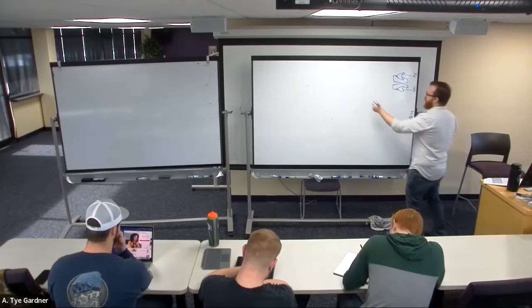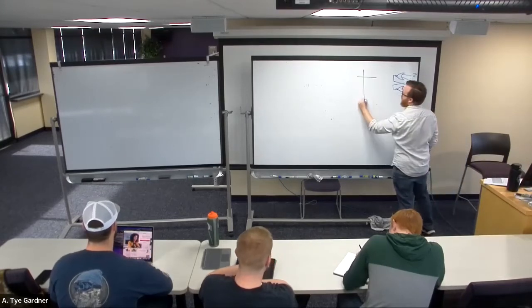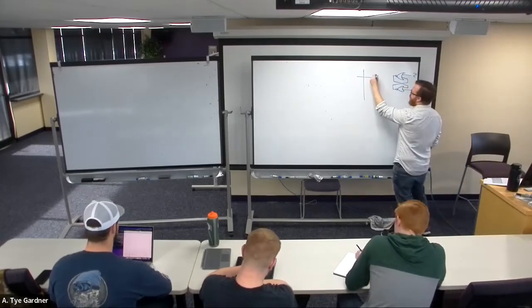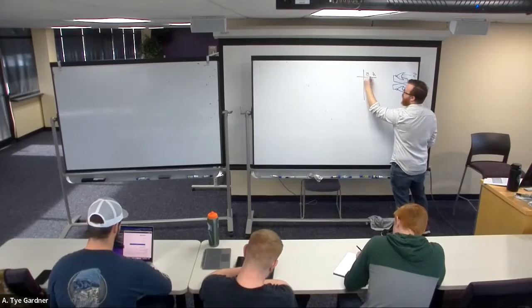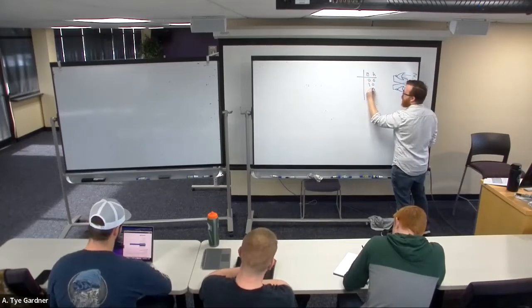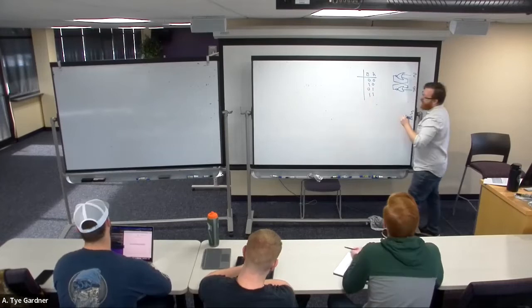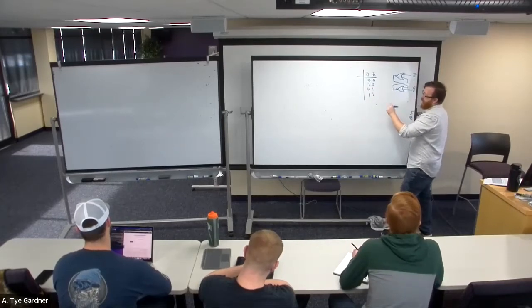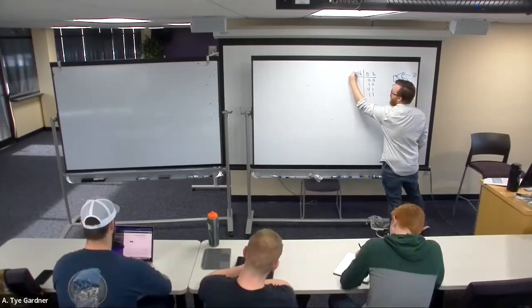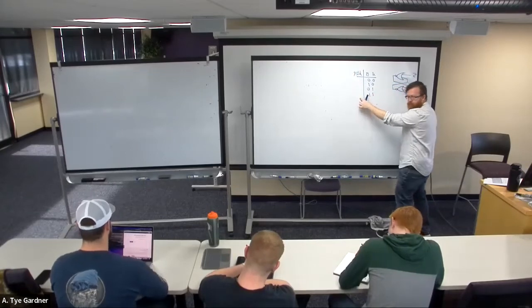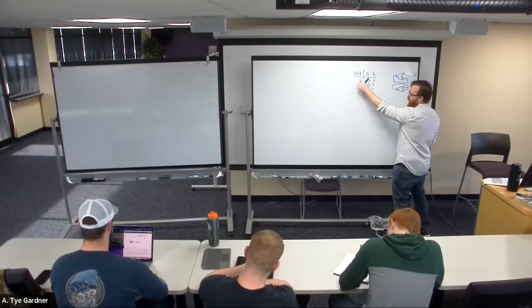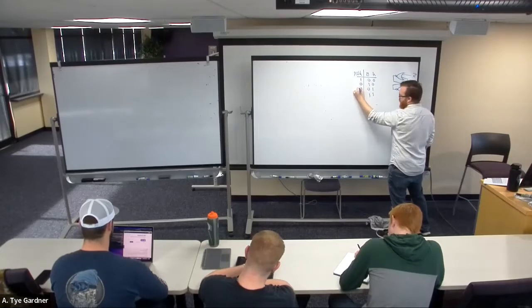And to do that, it turns out it's really helpful to start off just explicitly writing out the truth table for a NOR gate. So the NOR gate, right, an OR gate would have a 0, 1, 1, 1. So a NOR gate is 1, 0, 0, 0, right?